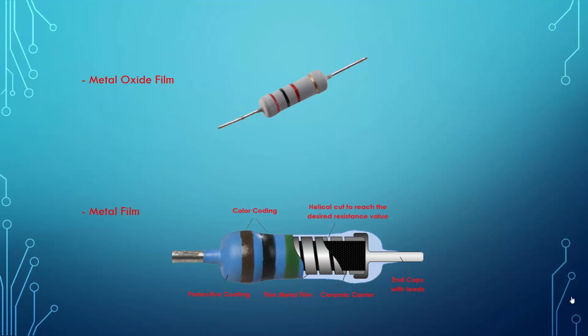Metal film resistor is available in thick and thin film versions. Most SMD resistors are of this type. The principal difference between thin film and thick film resistors is how the film is applied to the surface. Thick film resistors are cheaper and less precise than thin film resistors.